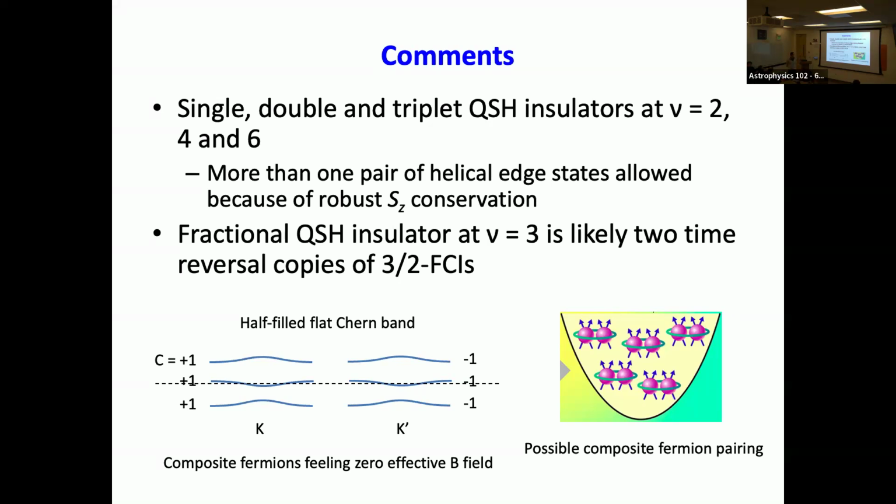But I think what you worry about is something scattering from one valley to the other and flipping spin, which is allowed. Not by momentum conservation, but by disorder. I think that takes an atomic scale defect to do it, and that may be one of the reasons that our devices are quite good: our edges are electrostatically defined, so it's a pretty smooth potential on the edge, and it's not really a physically terminated edge with lots of dangling bonds.